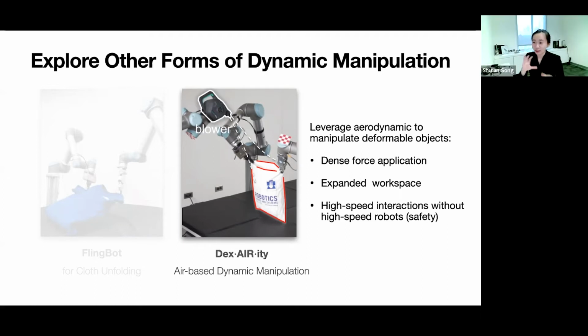Yeah, so how much the bag is opened, we measure from the side view camera. That is also how we get the reward values for training the policy. We have a side view camera basically looking at the volume of the bag. And the floating value that you see is basically the current size of the bag divided by the maximum size.